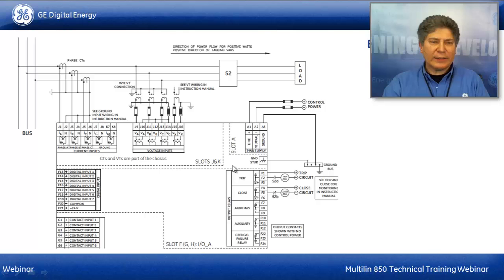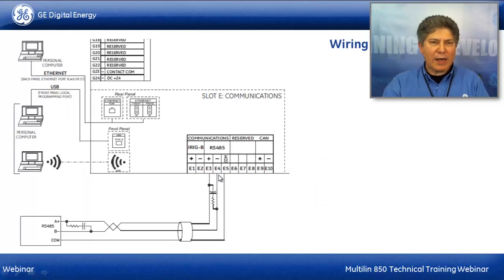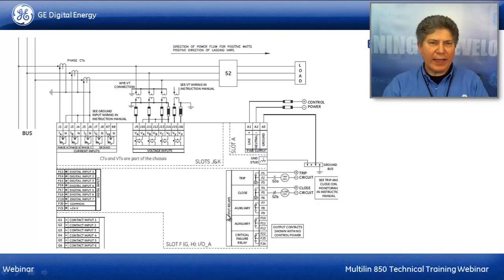All right, from an electrical point of view, I'll just go into this a little bit. So here's a wiring diagram for us. We'll go into a little more detail on this. The one thing I want to bring to your attention, once again, on the wiring of the control power, is that we just have a live, neutral, and a ground connection, and there's only one connection: the ground stud, separate one, going to the ground bus. The connection from the ground to the ground bus needs to be less than half an ohm, or else the ground isn't intact.